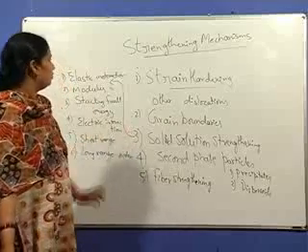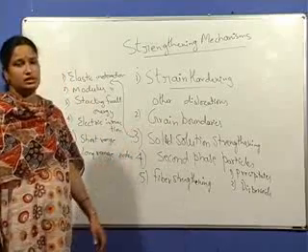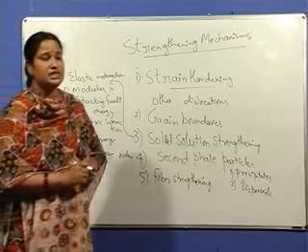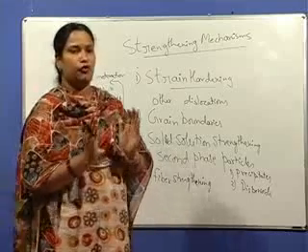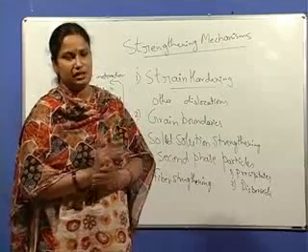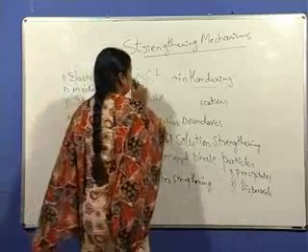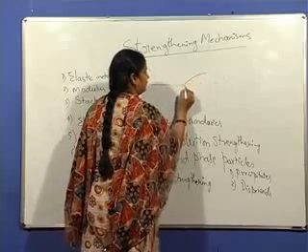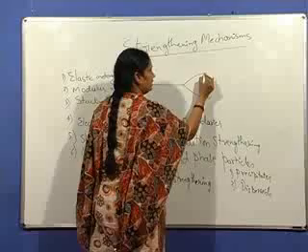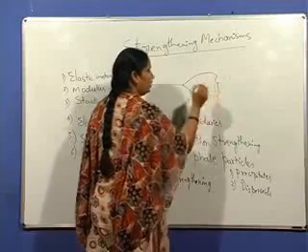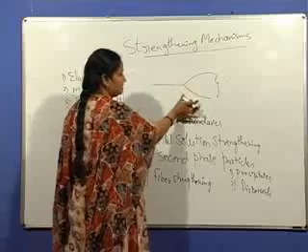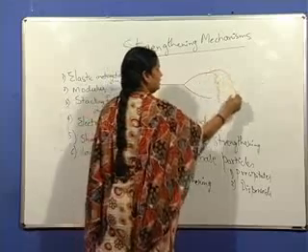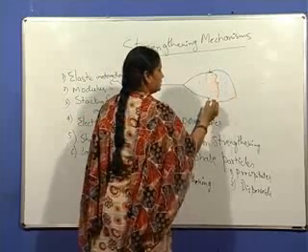The third type of strengthening in solid solution strengthening is stacking fault energy. Solute atoms segregate into the faulted region of the extended dislocation. An extended dislocation looks like this: two partial dislocations, and in between there is the faulted region. So this is an extended dislocation which has dissociated into two partial dislocations. These two are known as partial dislocations.